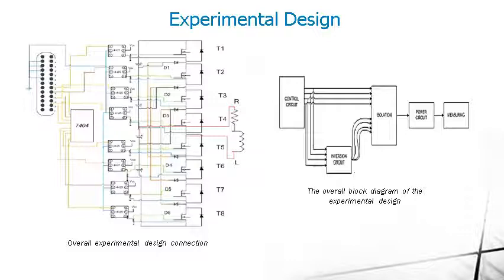The amplitude of the reference is equal to 4 volt peak to peak, which is centered in the middle of the triangular set. The four trains of pulses that are exported through the parallel port will be inverted using the 7404 logic NOT gate to operate the lower switches T1, T2, T3, T4. The 8 trains of pulses obtained from the parallel port and the inversion circuit will be isolated in the isolation circuit using a 4N25 optocoupler to isolate the power circuit from the computer, to prevent any damage to the computer because of any fault in the power circuit,